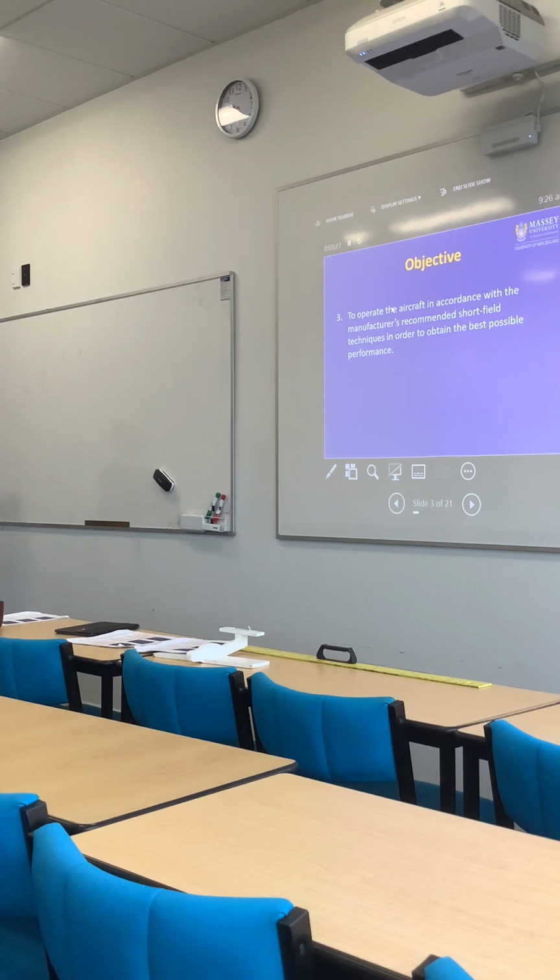Hence why the group rating is so high. You know, it's pretty unusual for a 4-seat aeroplane to have a group rating as high as 8. 172s are typically 4 or 5, and they weigh the same. So it's unusual. So that's the reason. These were European-built aeroplanes designed for long, sealed runways, not for the short grass runways with slope that we often have in New Zealand. So that's just a tangent. You don't have to go through that with your students.